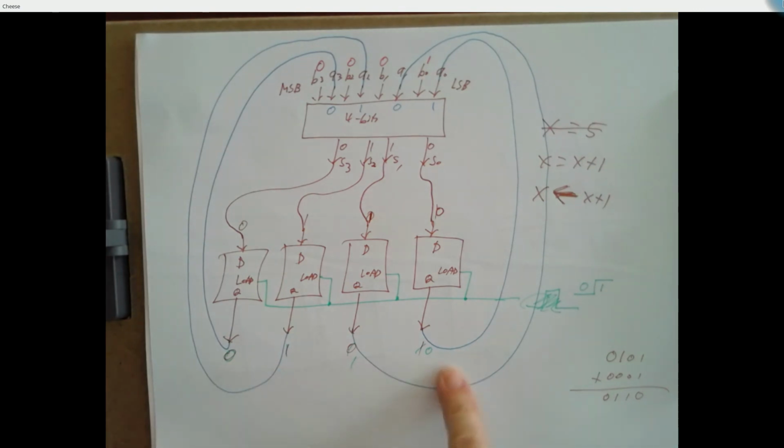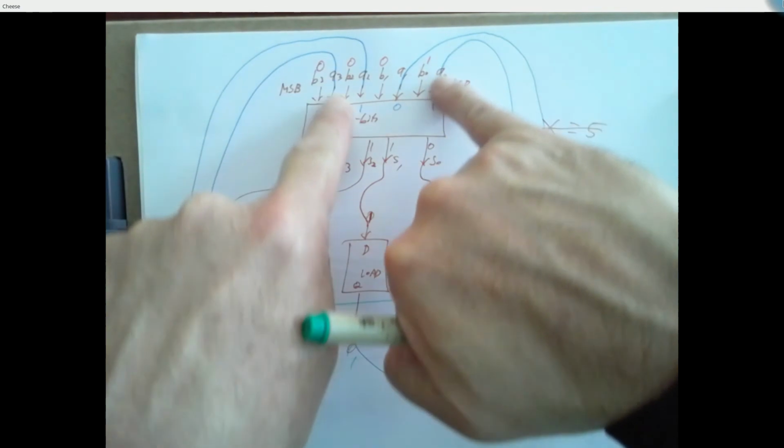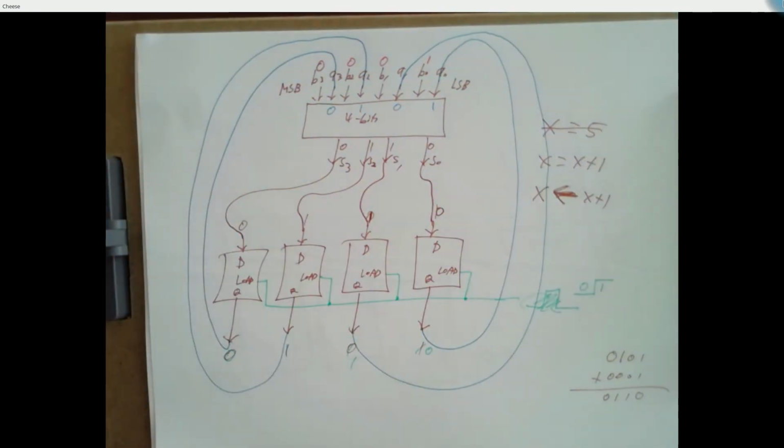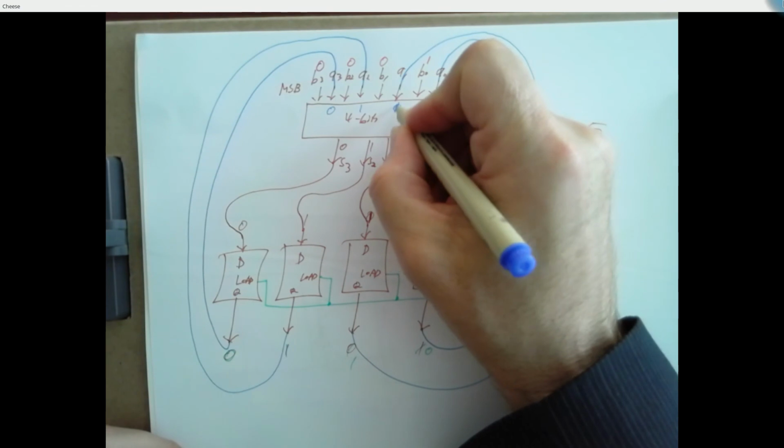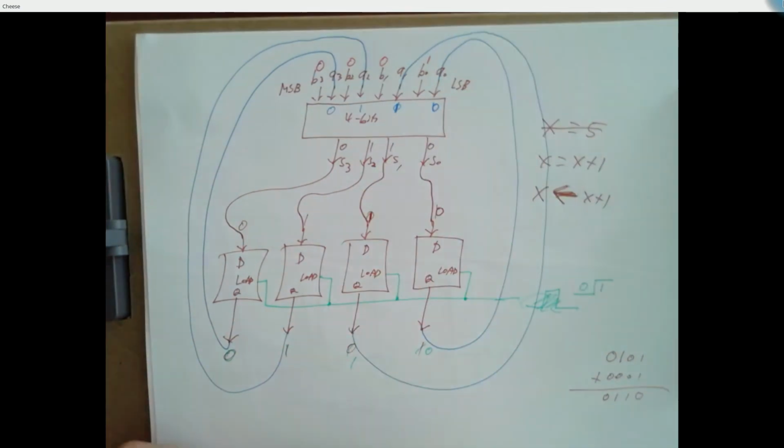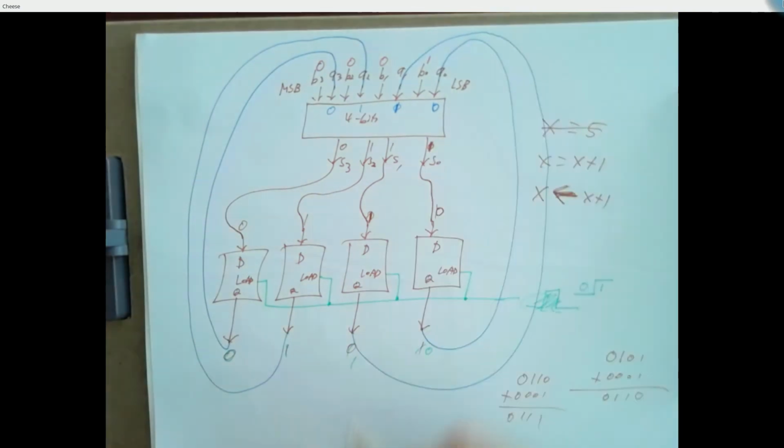All right, we have a 0 and 1, 0 coming out of here. What happens next? These come around up here, and now these A inputs are 0, 1, 1, 0. And the B input is still 0, 0, 0, 1. And so this is now doing the calculation. And the output of this adder is now 0, 1, 1, 1. What happens next? Haven't turned off high.